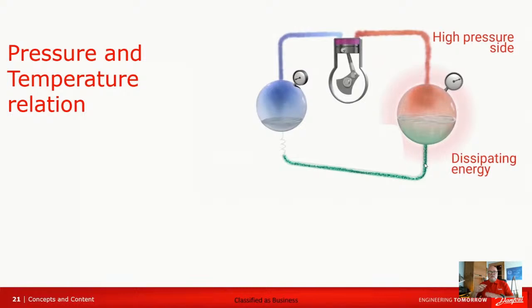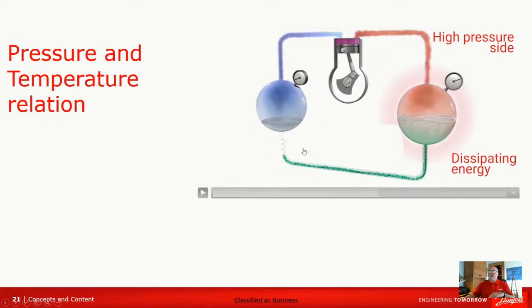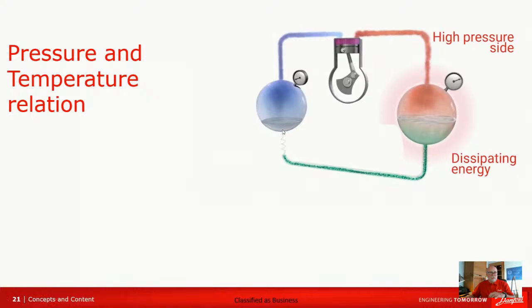And the importance of subcooling is that the lower the temperature of the liquid is, the better you are capable of utilizing the evaporative mechanism, so to speak. Not that you could cool it down to minus something.